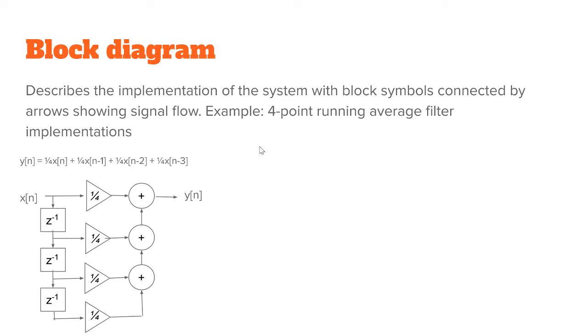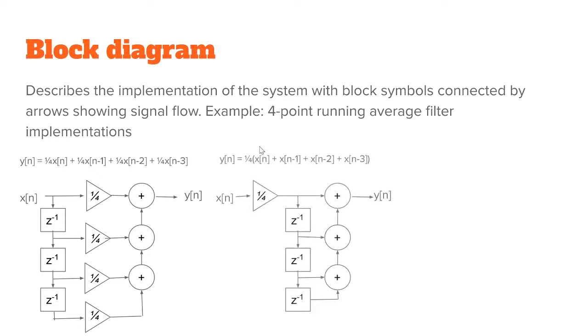For example, here, if you think of this kind of block diagram, this would definitely waste some resources. We have 4 multiplications of numbers with the same multiplier. So doesn't it make sense to move the multiplier in front as a common multiplier? Still the same difference equation, still the same output for the same input.